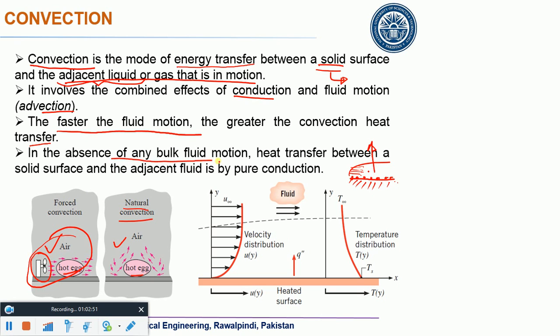In the absence of any bulk fluid motion, like the motion of air or water, where bulk means a larger group of molecules, heat transfer between a solid surface and adjacent fluid is by pure conduction. Just like if you put tea in a cup with no motion of the liquid molecules, placed on the table, and once you touch the cup you feel it's hot.